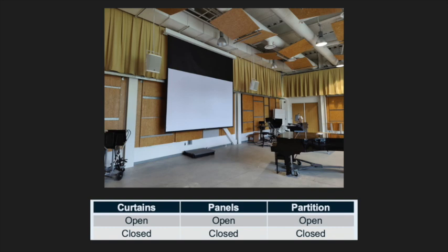In order to measure the room in its current state, we must conduct some measurements. These measurements are considered standard practice and generally provide an appropriate representation of a space's acoustic properties. The reverberation time, RT60, is a measure of the reverberation time by a reduction of 60 decibels. This is related to T30, which is the same concept but scaled by a factor of 2. T30 is used generally when background noise is relatively high, such as in this case.